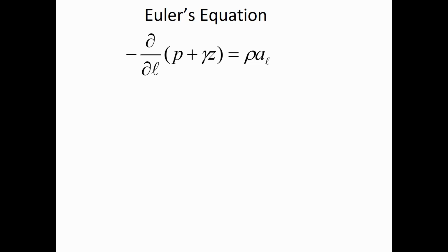So when we were using the hydrostatic equation, we were saying that fluids were not moving. And so we need some way to account for fluids that are moving with respect to position, which is convective acceleration, which is non-uniform flow. And sometimes we're going to have fluids that are moving with respect to time, and that's local acceleration. And that's what Euler's equation does, it helps us to predict changes in pressure that arise when there is an acceleration other than gravitational.